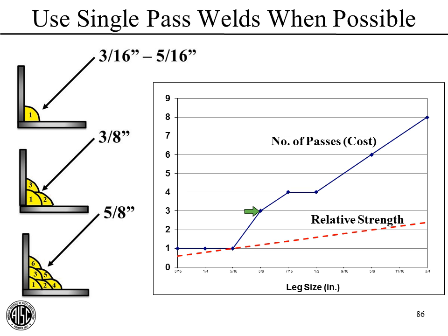So this leads us during design to decisions such as, imagine I can make the weld a little bit longer, and then I can get away with going from a 3/8 to 5/16. Well, it's a no-brainer there. So we need to be cognizant of this. 5/16 is kind of our magic number, and the price really goes up after that.